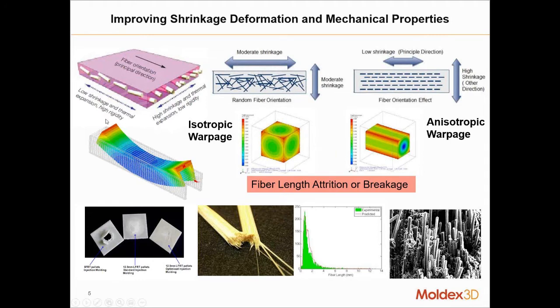As I mentioned earlier, the mechanical properties are going to be much improved because those fibers are rigid. Now, that increase in material properties comes at an expense. Transverse or orthogonal or 90 degrees to that fiber orientation direction, you get the absolute opposite situation occurring.